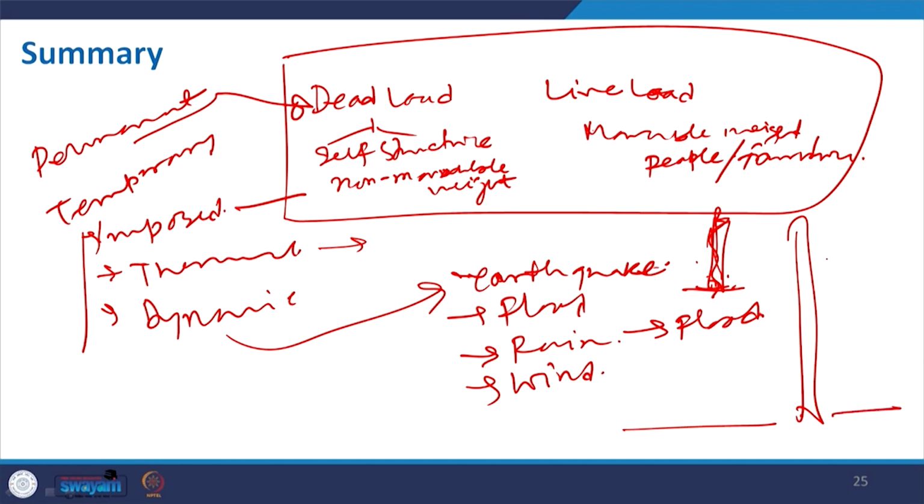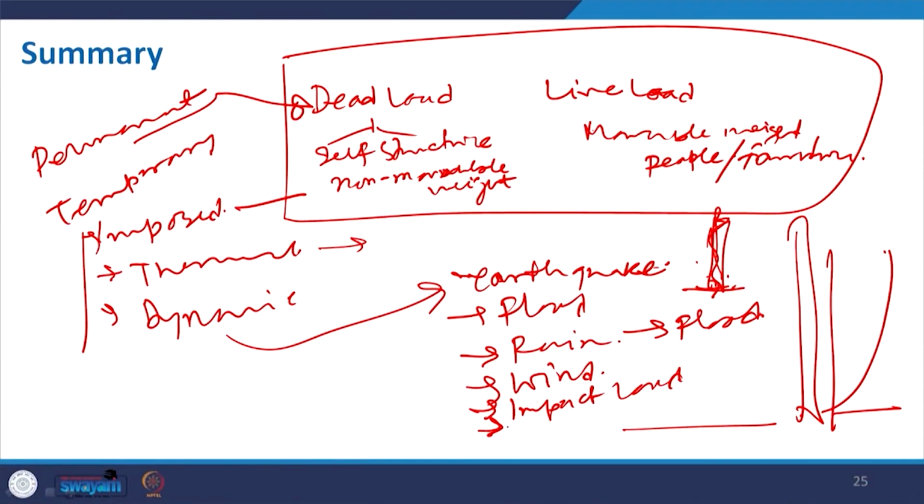The moment you go up, wind velocity will be more, as we discussed. And apart from that, we also discussed the impact load. All of a sudden you throw a heavy bag or some equipment on the floor, and that will create some impact on the floor or the wall. And then we also discussed the resonant load, which is very vital when we have such gatherings. With music, when multiple waves synchronize each other and propagate, they create a huge load on the structure. So, all these loads that we discussed today